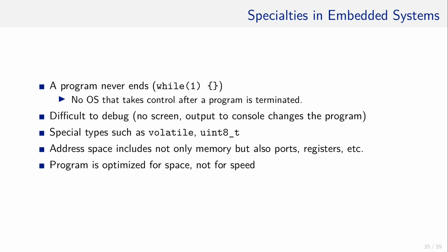However, in embedded systems, speed is secondary. In fact, they just have a few megahertz of clock speed, which is magnitudes slower than your PC whose CPU sleeps at, for instance, 800 megahertz, a range that is out of reach for most embedded systems. Hence, while we have enough patience for computation, we have limited memory space. So the priority shifts from fast execution times to asking the compiler to make the binary smaller, using maybe fewer instructions that are eventually slower in execution.